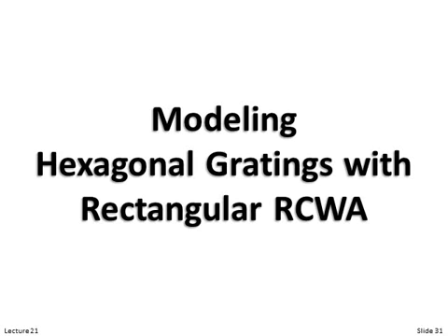The radio frequency folks that design frequency selective surfaces will tell you that in hexagonal arrays, the onset of grating lobes is farther out. What this means is that we can get away with a rather large spacing in a hexagonal array compared to a square array before we start diffracting into higher order modes. So there's some benefits to hexagonal gratings.